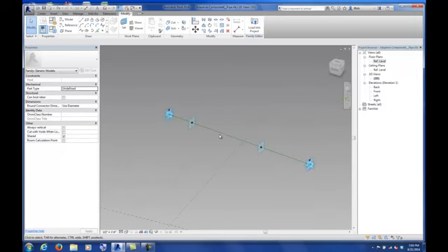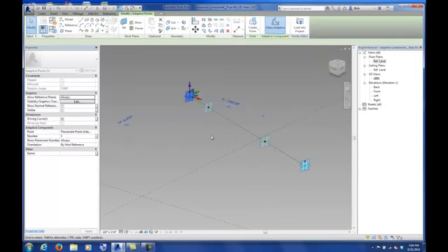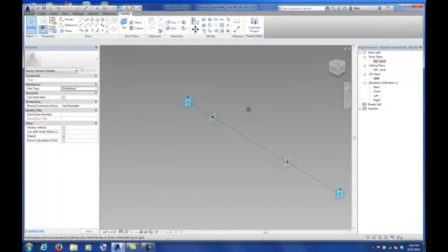If you're familiar with Rhino and the sweep command, or in SketchUp, the follow me command, anytime you want to extrude something along a path, you have to make your profile perpendicular, or typically you're supposed to, to the cross section of that line. And then you can pick the line as your path, and then you can pick the other profile, and it makes that extrusion follow wherever that path goes. Essentially what these planes are doing is making it so that no matter where this line goes, I will know that I have a perpendicular plane to that line. So it's kind of a nice feature.